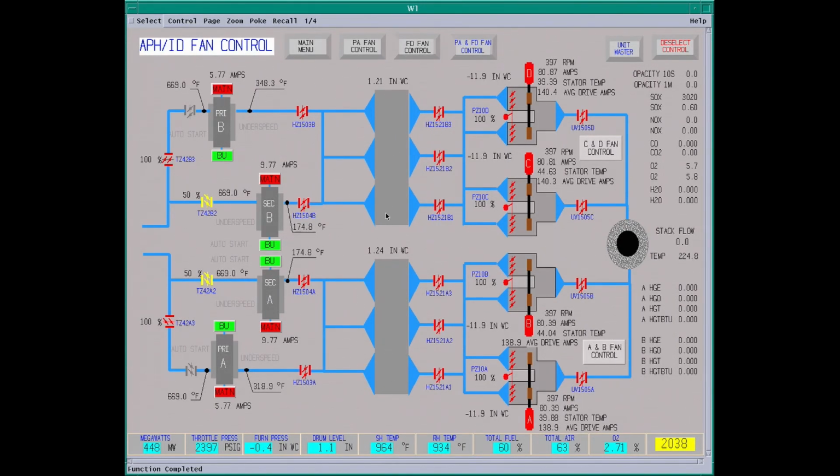This is the precipitator. Bill Hennings uses electrostatic precipitation. These are the ID fans. They're variable frequency drive motors. So the airflow looks good. We have these dampers full open, trying to get all the heat we can to the pulverizers. The low loads is going to be a problem. You have to play with the dampers and try and get more heat to the pulverizer so the coal grinds well, gets the moisture out of it.